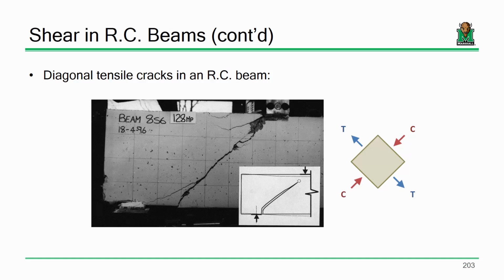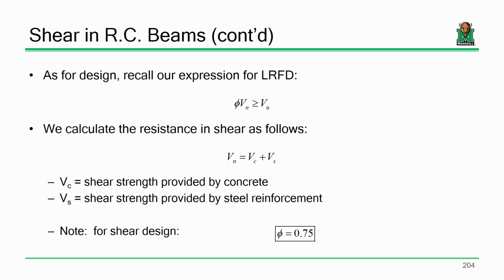See that? It's opening this way, which is the direction that we're seeing tension. Concrete is strong in compression, but it's weak in tension, okay? Make sense? If you look at shear buckling in steel beams, it's kind of the same phenomenon, only instead of the material cracking, it buckles in the opposite direction because of the material being in compression. So, all right, make sense?